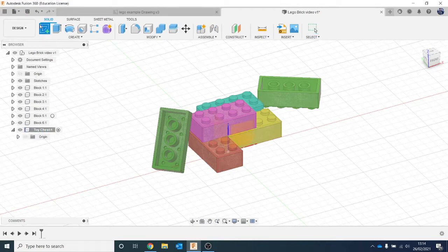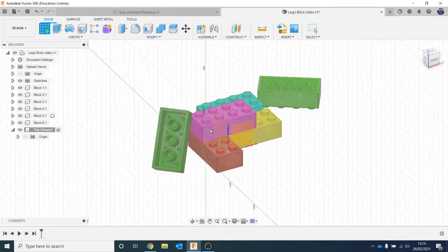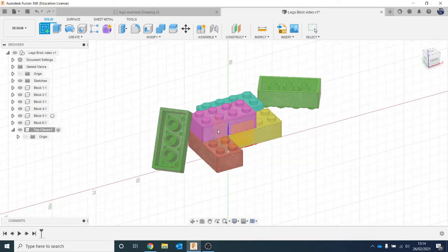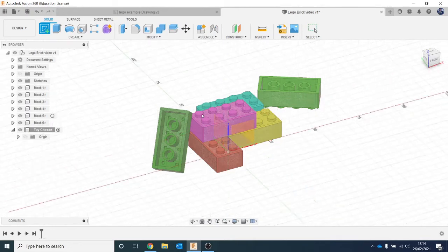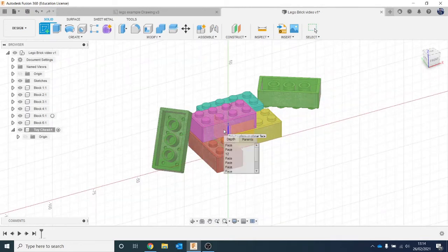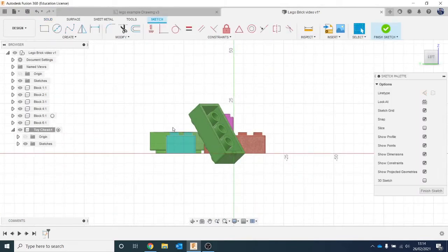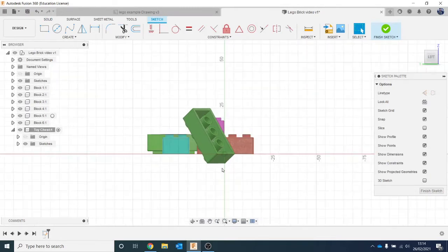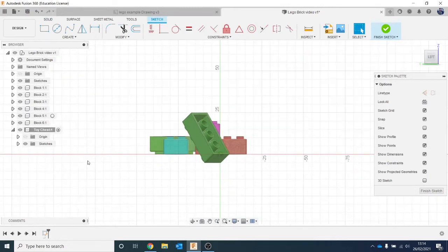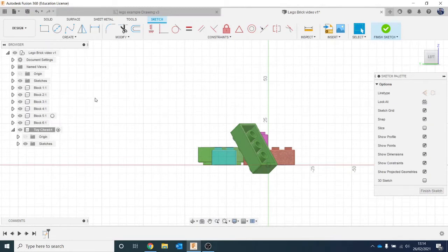Okay, so I'm going to go on sketch and I'm going to go on the side plane. Now at the minute I can't reach it because my models are in the way. But if I hold down the left key of my mouse, I can click it that way. That will let you pierce through anything that you've got. Now I've realised, of course, I need to move this model up a little bit. That's clearly going to be going through the floor a little bit later.